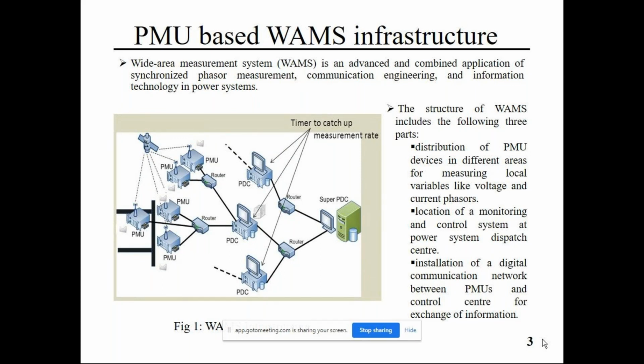You see the power network inherently, when you start from the generator, the classical model, if you are taking the saliency, if you are modeling the primitive model of the generator and the time varying form of the inductance, and correspondingly you are formulating the differential equation for the same, and taking all the things into account, this equation is manifested into the aggregated form of the generator, transformer, frequency sensitive model of the transmission system and other frequency sensitive loads also.